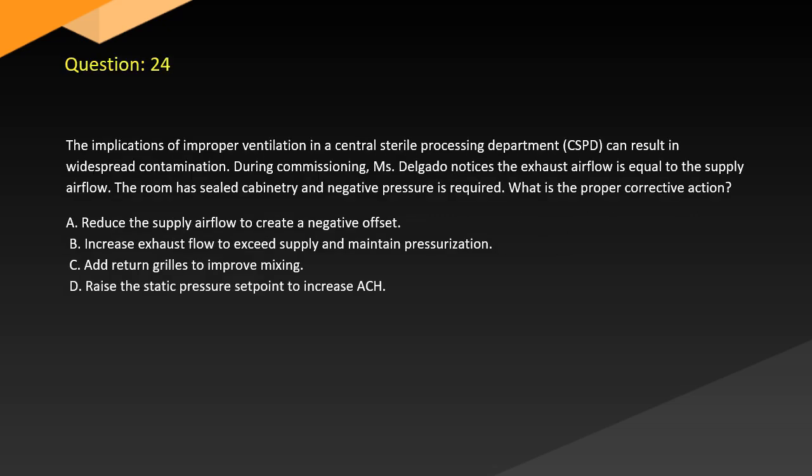Question 24. The implications of improper ventilation in the Central Sterile Processing Department, CSPD, can result in widespread contamination. During commissioning, Mr. Delgado notices the exhaust airflow is equal to the supply airflow. The room has sealed cabinetry and negative pressure is required. What is the proper corrective action?